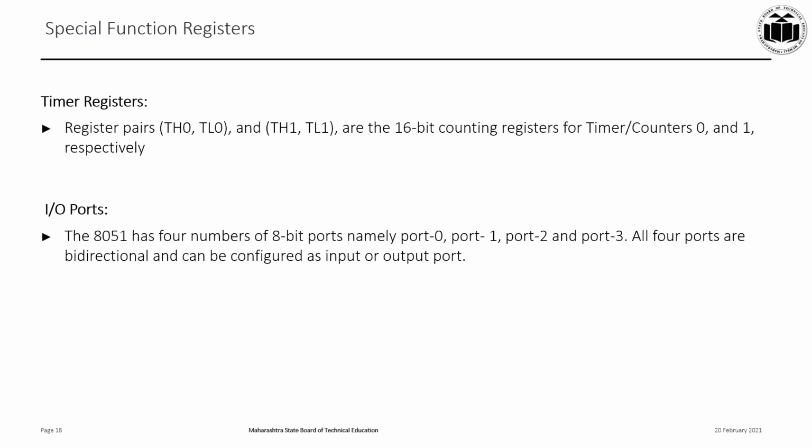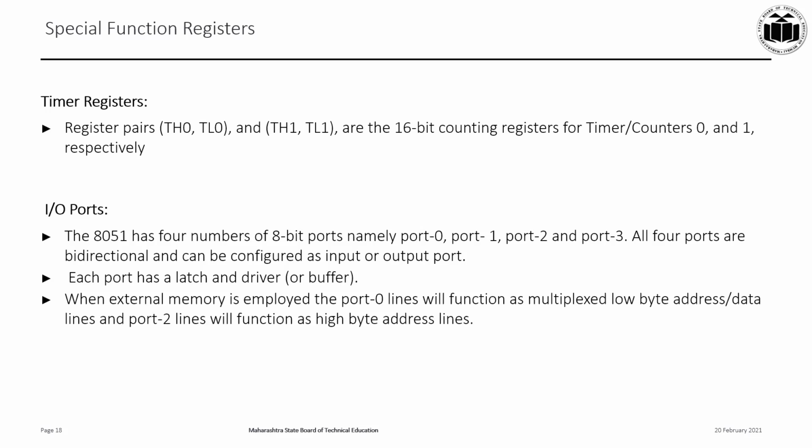I/O ports. There are 4 I/O ports, which we have discussed initially also. These 4 ports are bidirectional and they can be configured either as input port or output port. Each port, as we saw in the architecture diagram, has a latch and a driver.